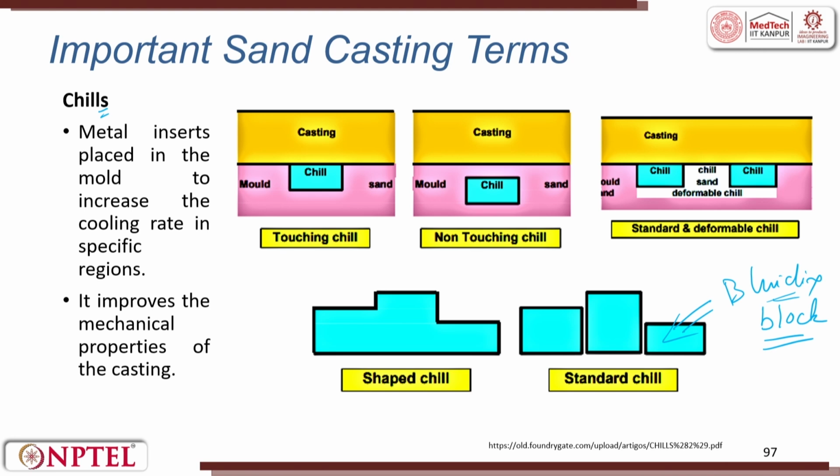So, with this, I am sure you will now appreciate and understand sand casting. How is a sand casting made? In sand casting, what are all the parts? Cope, drag, mold, core, core print, sprue, riser, vent. These are the things we saw.